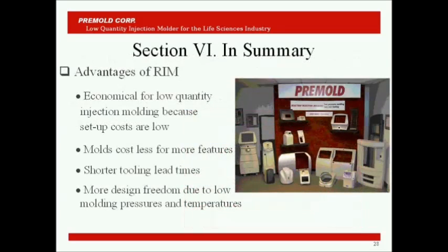Okay, I'll do that. RIM is economical for low-quantity injection molding because setup costs are low. This is because reaction injection molding is a low-pressure, low-temperature process. Therefore, RIM is well-suited for medium and large enclosures with complex geometry and high cosmetics. This is especially important for low-quantity housings used on medical devices and lab instruments.